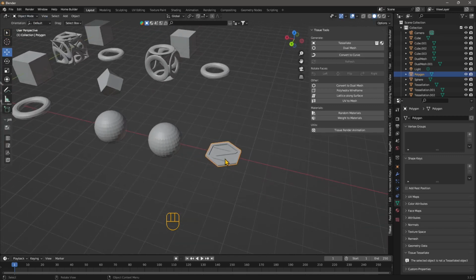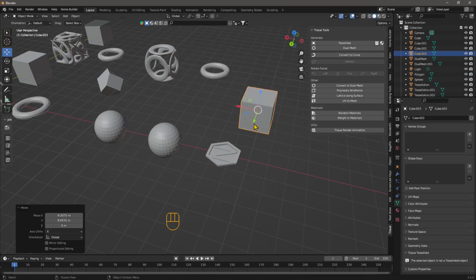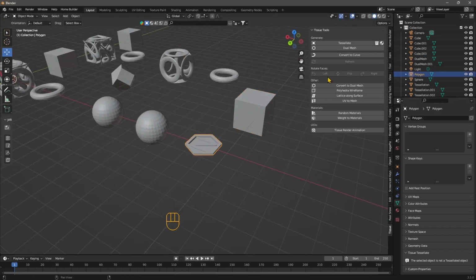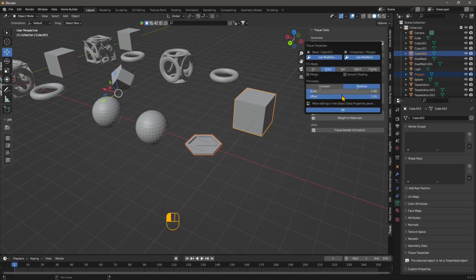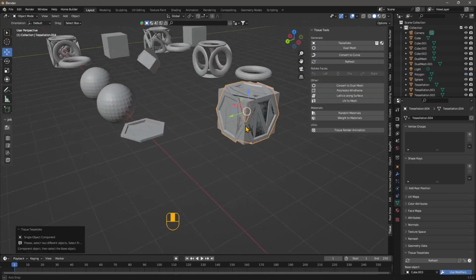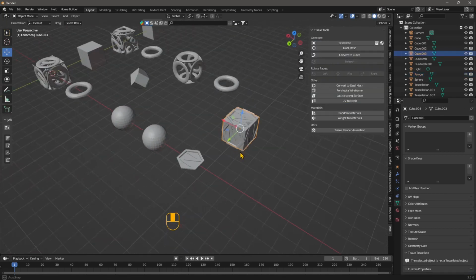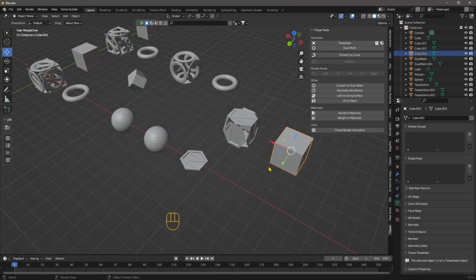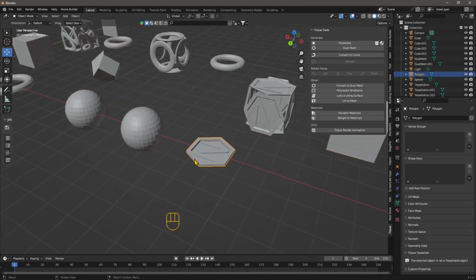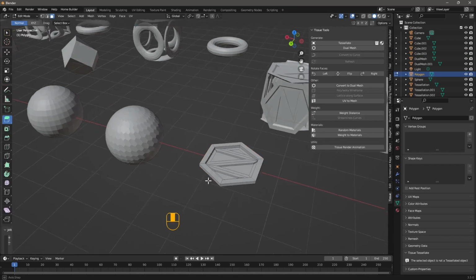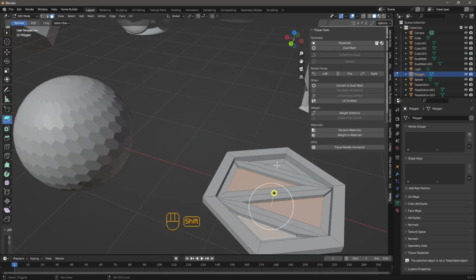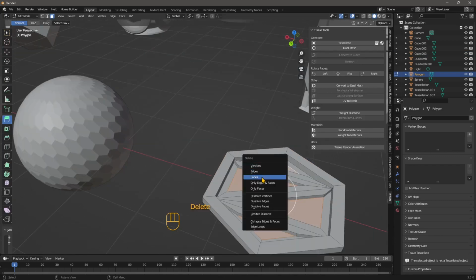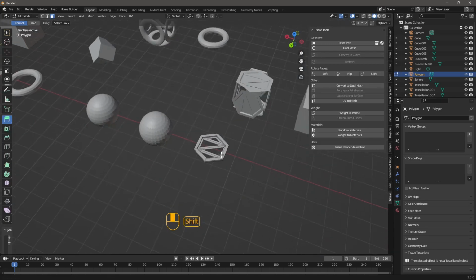So first, try to test it with something simple like the cube. So if I take this one here, let's just go to select mode, and this will be the distribution, and do tessellate again. Okay, there you go. So you can see that it's working, even if these are not hexagons. And actually, I want to get rid of some of these. So delete those faces right there.